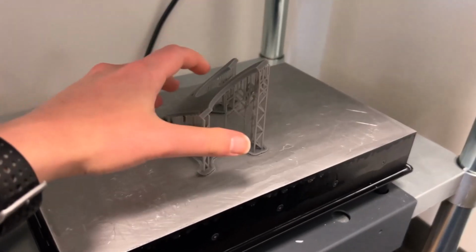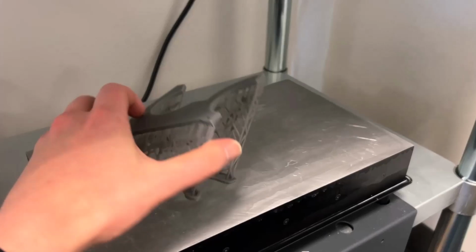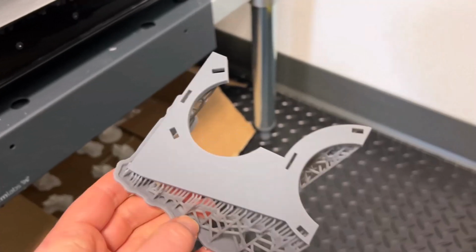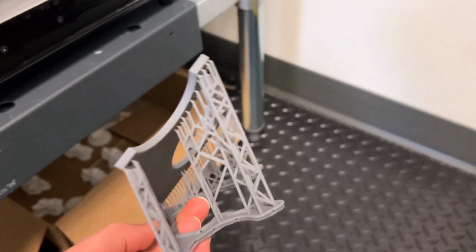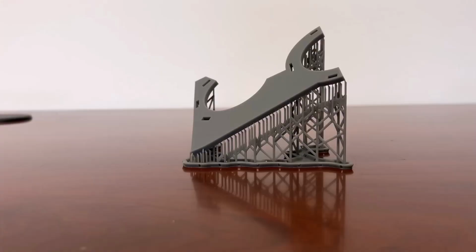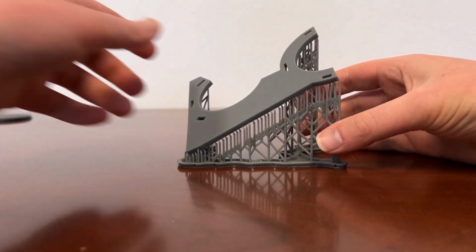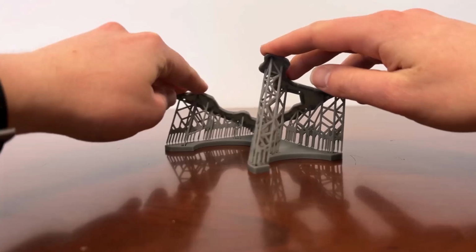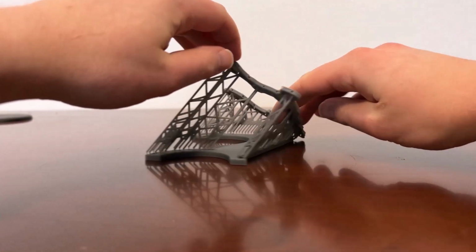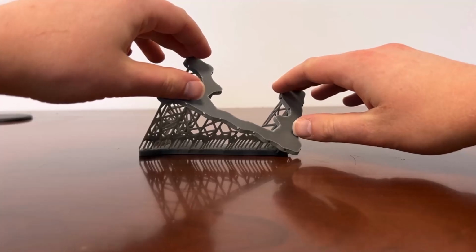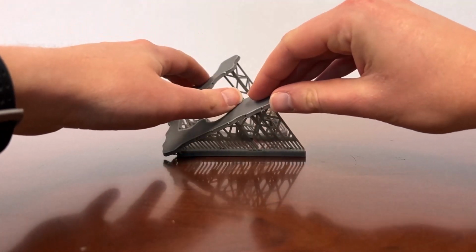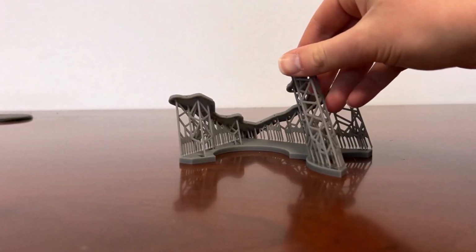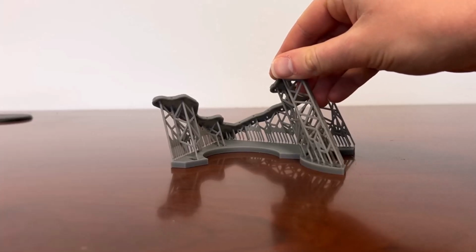Oh, and as promised, I went and printed that flat part that we looked at earlier. So here it is right off the build platform. You can see our supports match what we put in on PreForm, including that arced bit there, sticks way out high up. And just flipping it over on this flat surface, you can see we maintained a flat plane. You can't see any light peeking out from behind those edges, and there's no rock or anything on the part. So that was a good support placement strategy for flat parts, which as I mentioned, can be pretty challenging to support and orient on an SLA printer.